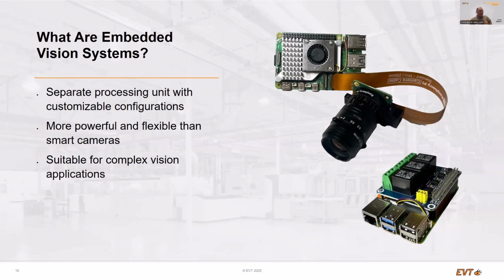When this restriction is not there, if you use these embedded platforms, you can use more powerful, mostly ARM CPUs, and run all the software which you run on any PC in general, as long as the software is available for ARM platforms. And of course, also because it's not so restricted in space, you find on these embedded systems nearly the same amount of main memory as you will find in a PC.